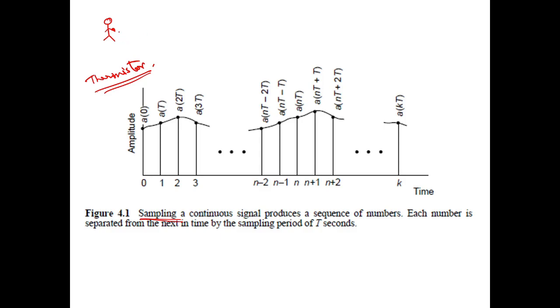Okay, so as you take the signal from here, initially we will have analog signal processing systems which do some manipulation on the sensor signal. So it is basically a hardware thing. For example, over here you will have voltage dividers and all these things, so that you can accurately measure the voltage drop across the thermistor, and then you want to record this, and then if you want to band limit this.